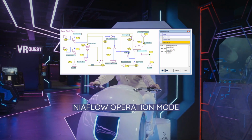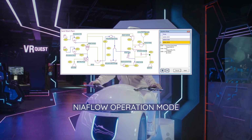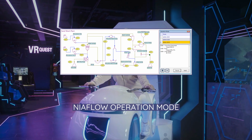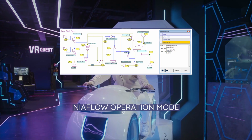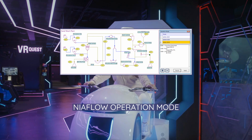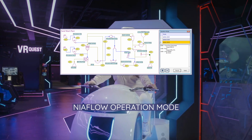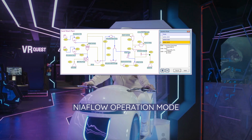Crushing, milling. Crusher and mill products are calculated assuming a linear behavior of the product PSD in either a double logarithmic or RRSB grid. Each type of crushing or grinding machine creates its own specific inclination of the curve. The inclination combined with the maximum particle size leaving the machine is used for product forecast.